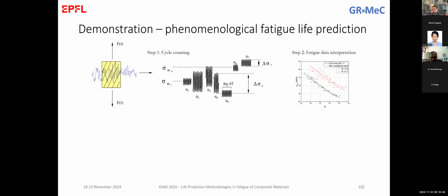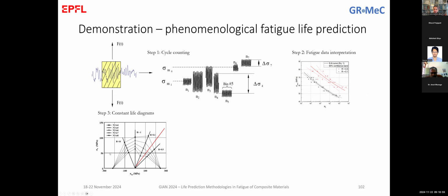You remember we discussed this yesterday and the day before? Constant life diagrams. Exactly. Here I have to talk about constant life diagrams, which, as we mentioned, are established by using some known SN curves. So the idea is to do some experimental investigations, estimate SN curves, draw the constant life diagram, and then, coming